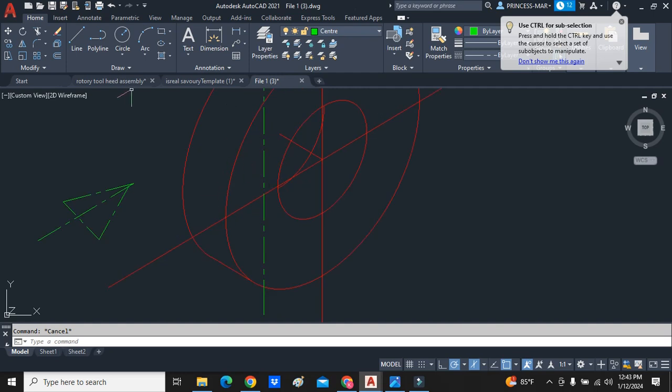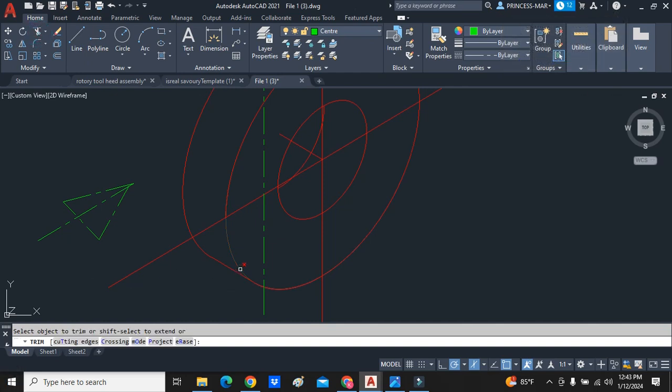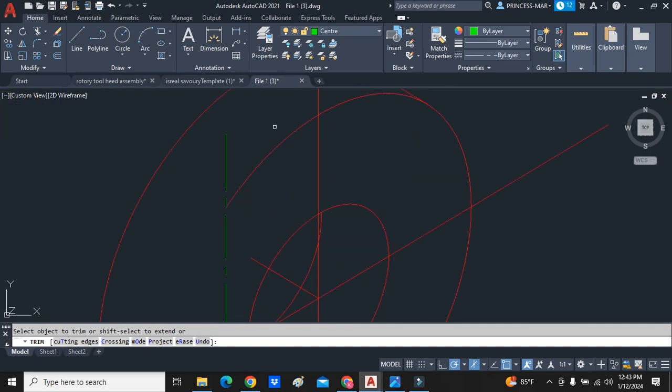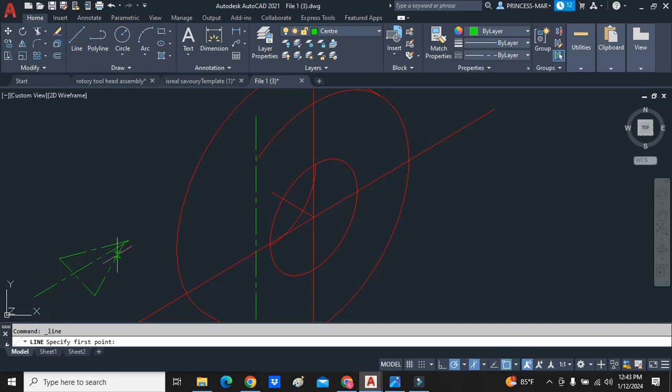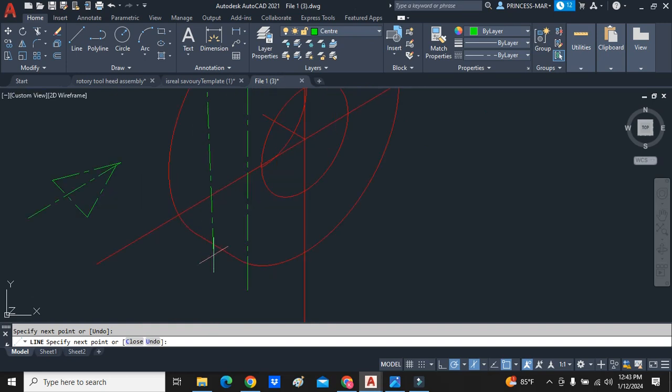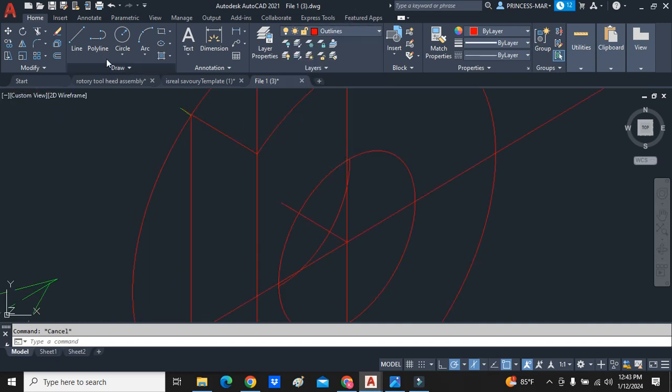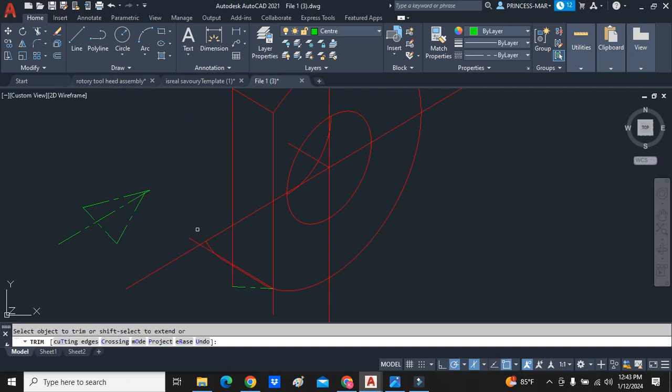Now, I'm going to remove that left piece now. I want you to watch. So for this front piece here, where it is cut, I remove that left piece. Now my question to you is this: top piece here, is it cut? No, sir. So when I look at the object in the direction of this arrow, I can see the part over here that is cut. It will be like a smooth line here coming down. I'll just make these lines solid now. And I'll just remove this.